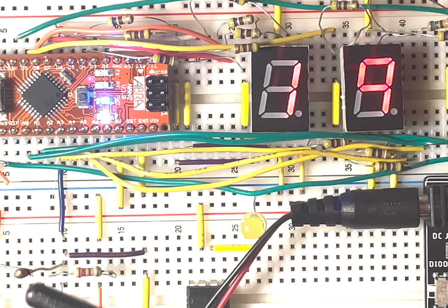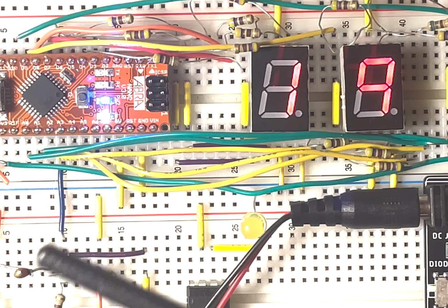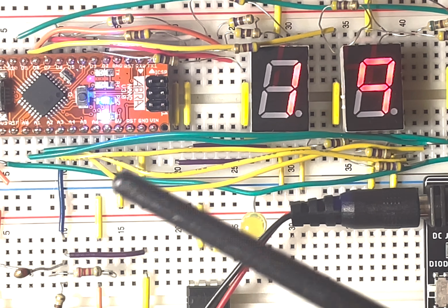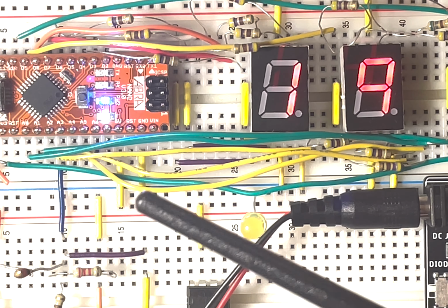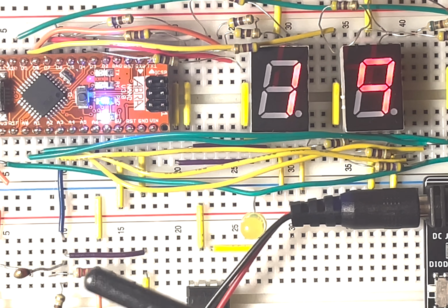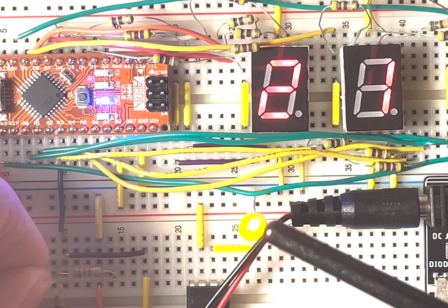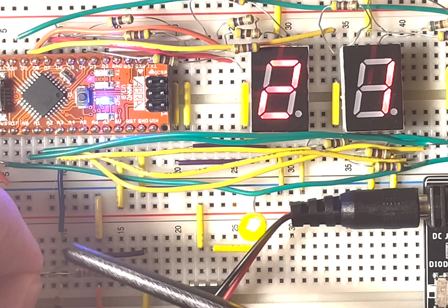While this is not possible with my current resources, I instead used a program with approximate values in order to find a set of Steinhart coefficients, which gave me something relatively close to the actual temperature. The circuit still works relatively well, but it's important to note that it will not be accurate unless you have the exact Steinhart coefficients. As you can see here, when I warm up the thermistor, the temperature increases. And in our previous part of the circuit, the LED turns on because the current is now greater on point C than it is on point D.